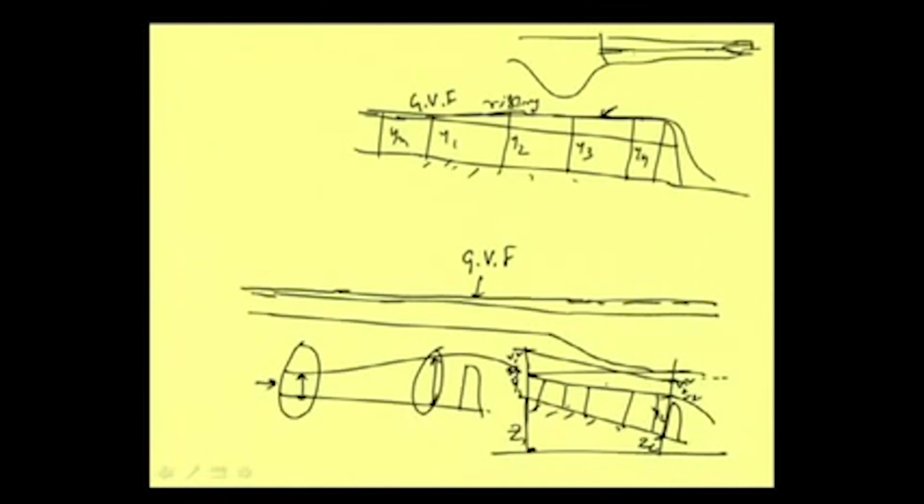It is so, this can be computationally checked, we can do the computation and we can check, and this is very important. Suppose for some reason we are making a barrier here, then water depth will be rising, and say bank level is here. Let me draw a phase diagram. Say our bed is this one and this is the bank level, and when uniform flow is occurring with maximum discharge, it is at this level. So, there is no question of overflooding. Of course, during flood time there may be flood, but generally flooding is not occurring.